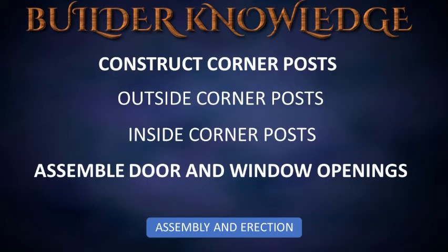Wall assembly and erection. First, we will construct the corner posts. All corner assemblies should be constructed from straight stud material and should be well nailed. For improved productivity, corner posts for a building are commonly assembled prior to wood-framed walls being assembled and may all be constructed at one time using a bench. Blocks should be held slightly back from the ends of the studs. Before nailing, ensure the ends of the studs align with each other. When framing corners, use full-length studs or short blocks.